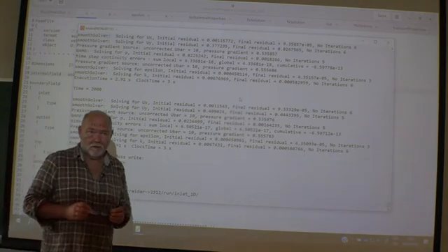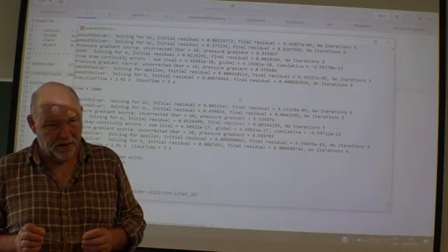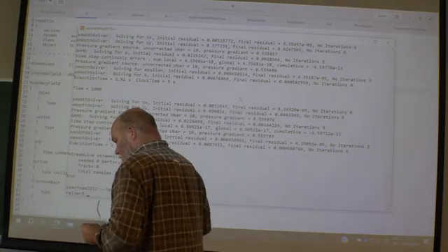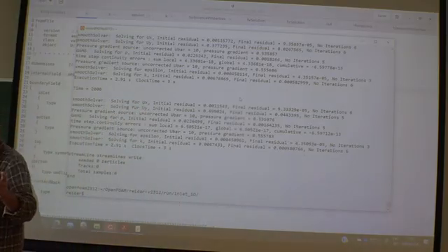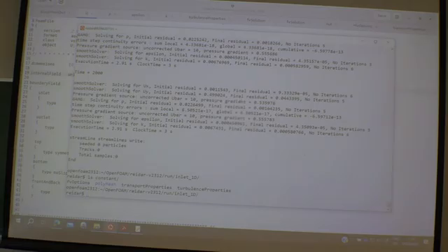Yeah? Do I actually copy the file with the options? Where was that from? Sorry, this file you needed to copy. Oh yeah, you need that file. Well, I'm not sure if you are allowed to use the same file if you have the same system. But I mean, the file name, that is called fvOptions. So then you can use the find command and search through all the tutorials and see if you can find it there as a file. That's one way.